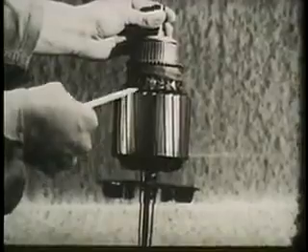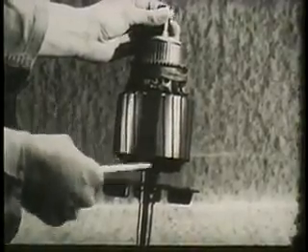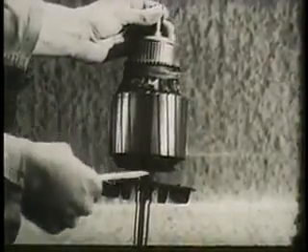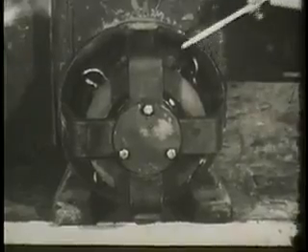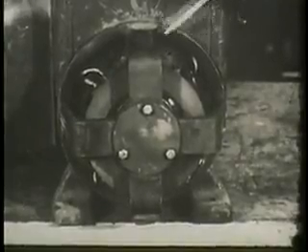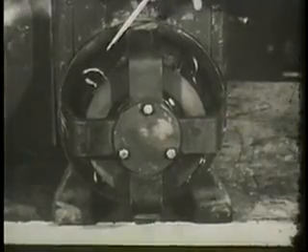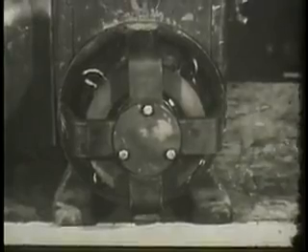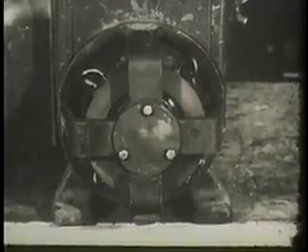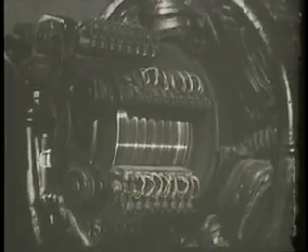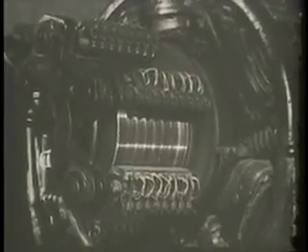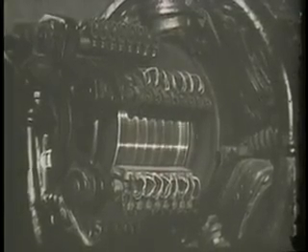Practical DC generator armatures have a great many loops wound on a rotor. The field is composed of many electromagnets. Together, these factors tend to create an almost pure DC output. An important problem in the design of generators is the prevention of sparking between the commutator and the brush assembly. The prevention of sparking depends on the position of the brushes.